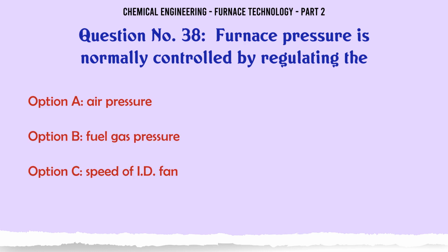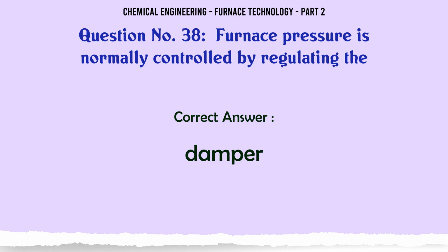Furnace pressure is normally controlled by regulating the A. Air pressure. B. Fuel gas pressure. C. Speed of ID fan. D. Damper. The correct answer is damper.